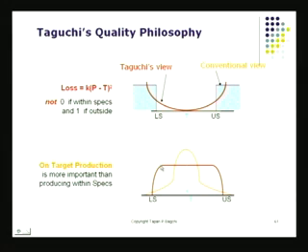As far as customer satisfaction was concerned, it turned out customer satisfaction was maximum when TVs were assembled with the philosophy of being put together with the target in mind, and customer satisfaction was not as high when they were put together with this philosophy of just meeting specifications. This is where we got the graphic feedback that it is best to produce parts and products that meet the target. So do not try to produce things that come within specification.